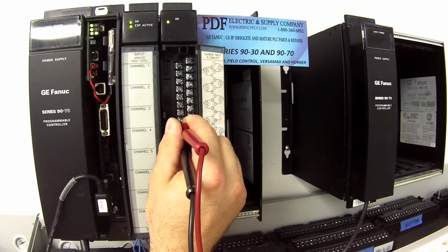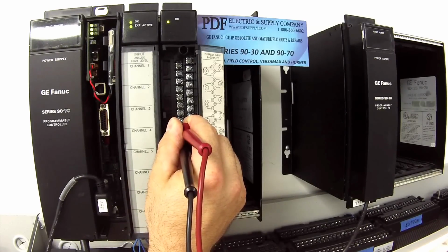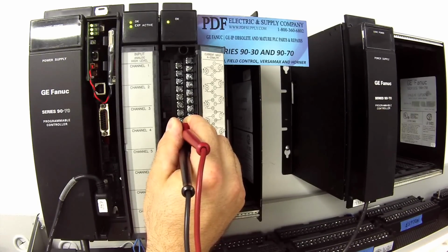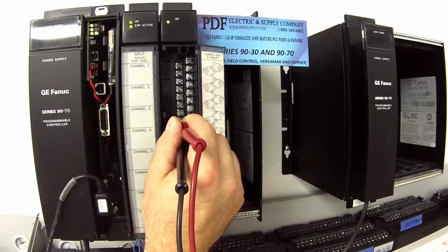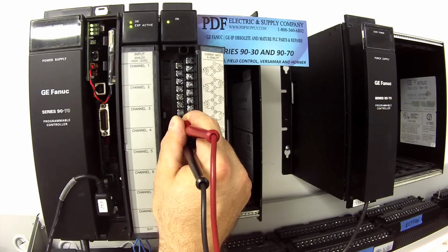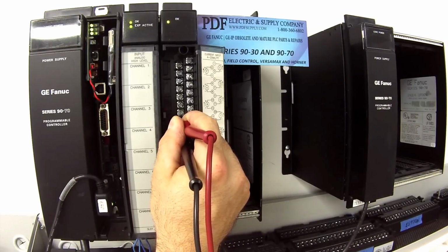If there's a particular channel that you think you might be having trouble with, on my generator I can increase or decrease the amount of milliamps, and I can watch on Proficy Machine Edition in the analog input table the value going down in very small amounts or going up in very small amounts at a time. And what I'm doing here is I'm making sure that the circuit isn't just stuck on its full value. So occasionally if these go bad and you put it on, it may give you a full value of 32,767. When you try to drop the value to see a lower value or a lower scaling and nothing happens, that usually tells me that the circuit is blown.